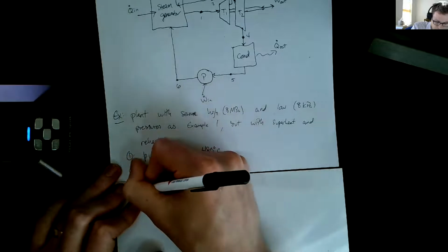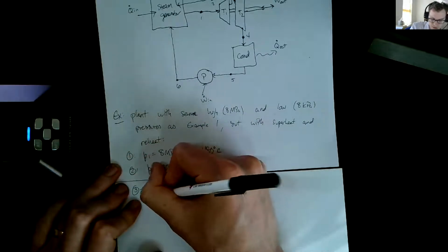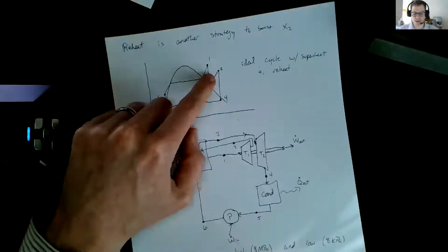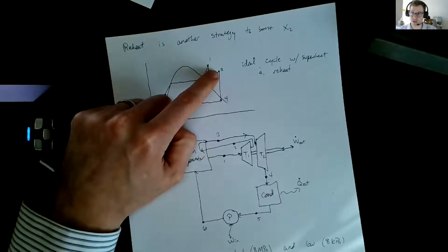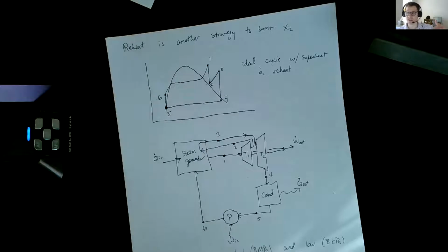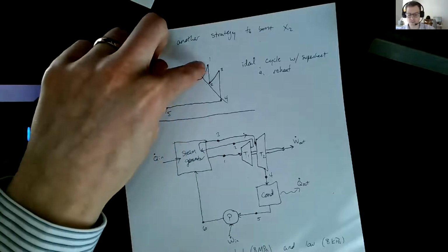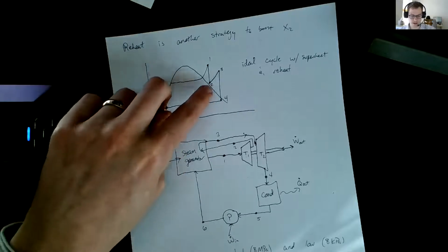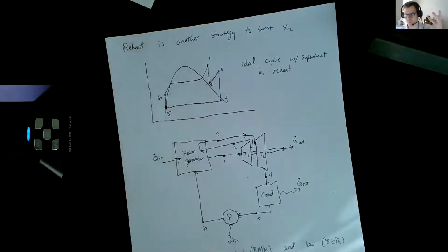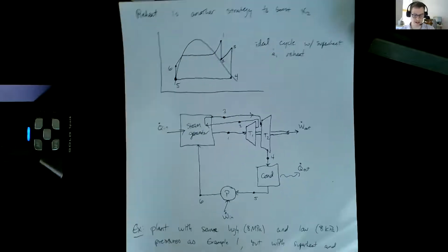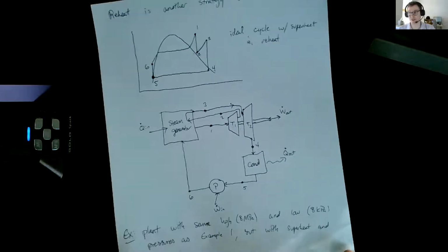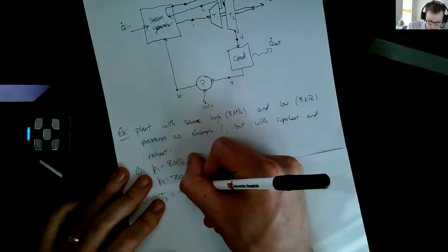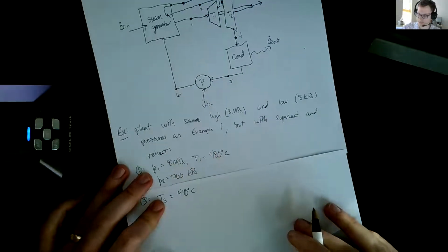And then state 3, the piece of information I'll give you there is that T3, which is the temperature going into the second stage. So really, when you set up these complex Rankine cycles, the data you need are the input states to the turbines, right? I'm giving you P1 and T1, and P2 and P3 are the same, which we'll show later on. So I'm being a little sneaky and telling you it's P2, but really it's also P3. And then T3 is 440 degrees C.